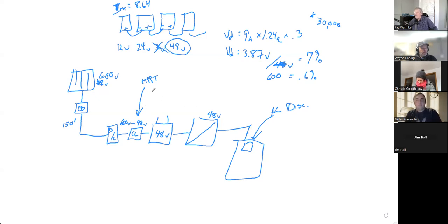Plus, just to make you confused even more, it's still a pulse width modulating charge controller. So it hasn't changed. It's just got this marketing buzzword of MPPT attached to it. It basically is what they call a buck boost charge controller. Comes in at one voltage, leaves at another, either up or down. So I don't know, did I confuse anybody, or does that all make sense?